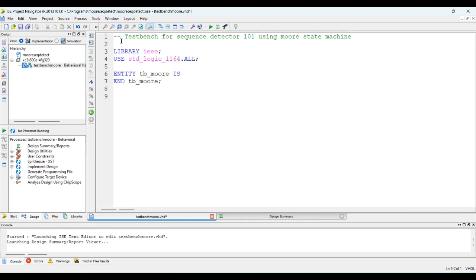So what I've done here is that I have declared a test bench entity TB Mealy, and it is a test bench entity which is used for simulation, whatever simulation we are going to create in the upcoming code. And I'm also testing the values, giving a lot of values. For the design unit, I'm going to describe the design unit using an entity.